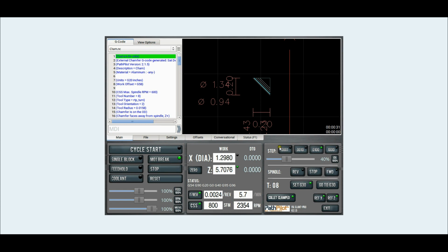Okay, on this side, here's your step. You can change this to adjust the amount of jog movement, anywhere between a tenth up to 100 thou, in steps of 0.10 basically. The jog speed, I've never actually messed with that. I assume when you jog with the dial that it's not at 100%, though it feels like it is. I feel like I've seen it go up to 60 inches a minute as I'm doing that, so I'm not entirely sure. Never used it.